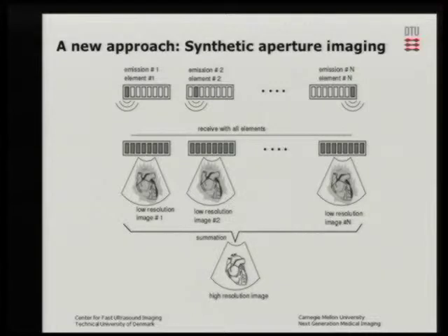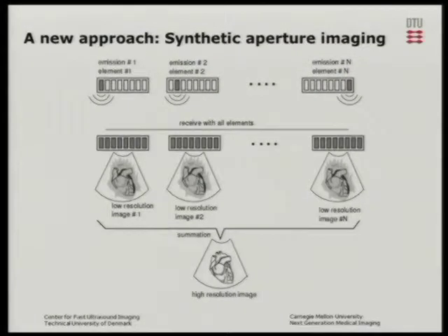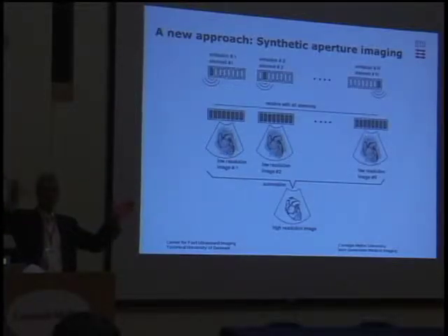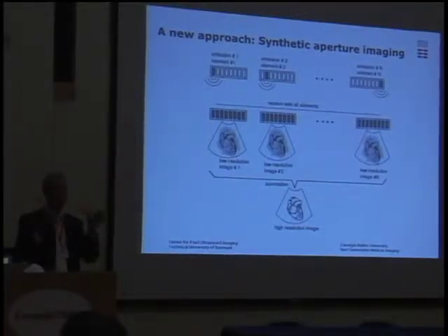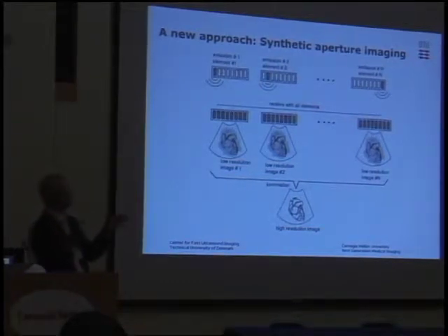Now I want to go to another place where we say, let's not look at the conventional thing where we go in a serial fashion in the same direction. Now I want to introduce synthetic aperture. In synthetic aperture, we use a small aperture and then we send out sound in all directions. And when we send out the sound in all directions and receive with all channels, we can actually formulate one image